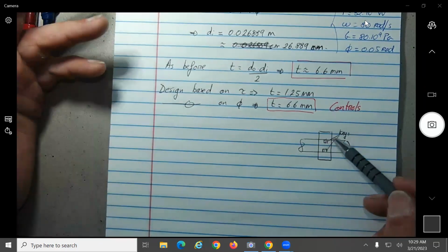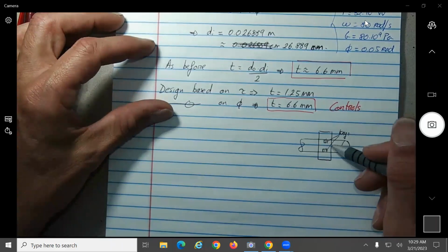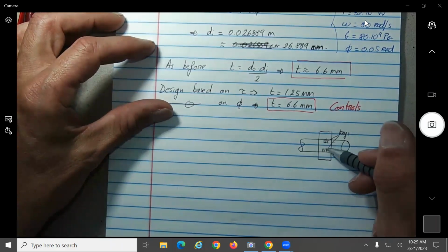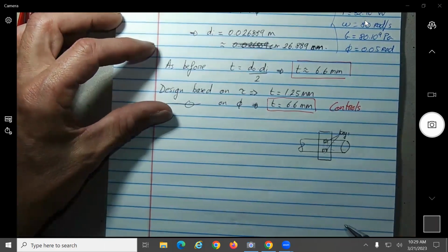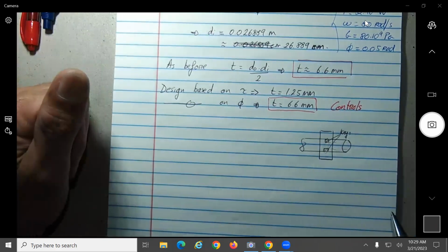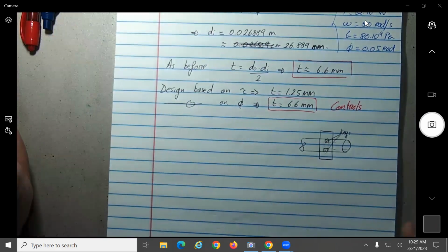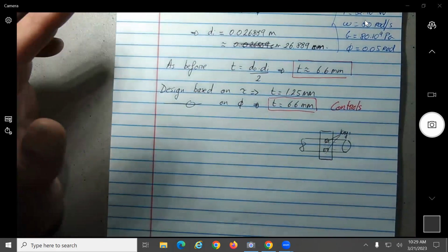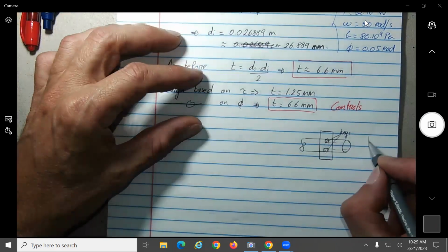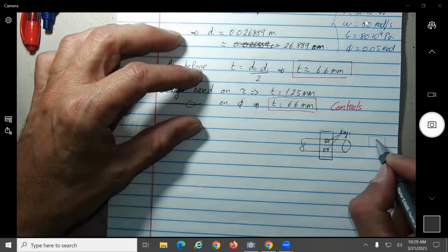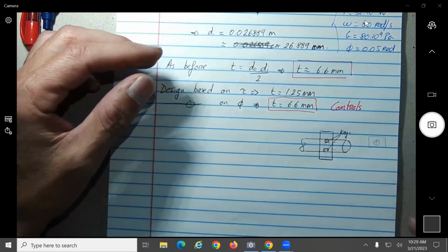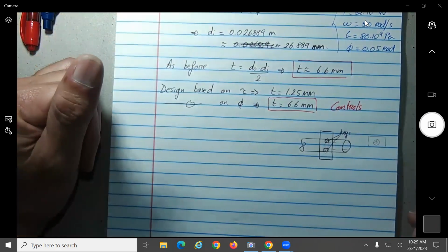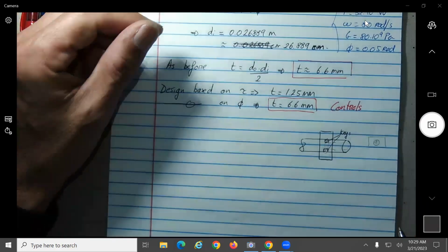A simple calculation would be to calculate the stress, and instead of the whole cross section resisting the load, you say it will be the internal one. But all this is generally managed by using what are called concentration factors, that we'll cover later on. It's the same thing as if you have a plate or a beam that is full, and then you make a hole inside. It is not going to have the same resistance for the normal stress, no? Anyway, this is a key.